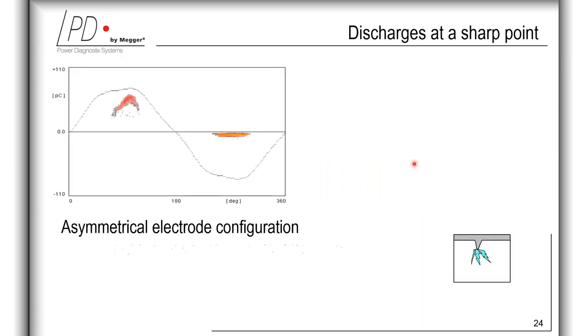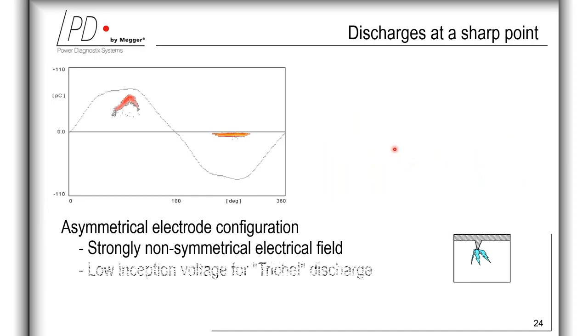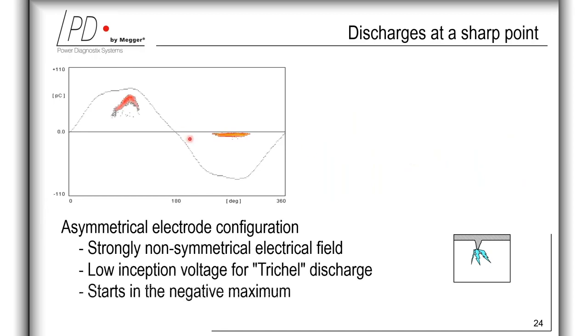So in this slide, we see a partial discharge activity, which is more controlled by the strong asymmetry of the electric field. And this is an example of a point-plane discharge, which is a candidate with strong differences to the processes of partial discharge in spherical voids. In case of such a sharp metallic tip, unlimited starting electrons are available. And therefore, due to strongly enhanced electric field at the tip, the critical electric field is firstly reached at the tip in the negative polarity.